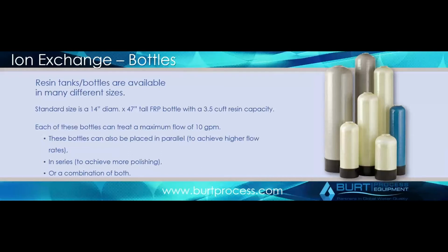Again, if you were targeting something which requires, say, an ASTM 2 spec, 1 to 2 megaohm, you don't have to constantly polish your high purity water through a resin bottle. You can very easily just have it flow from the RO through the resin bottles, and then maybe even have a slipstream coming back to it.